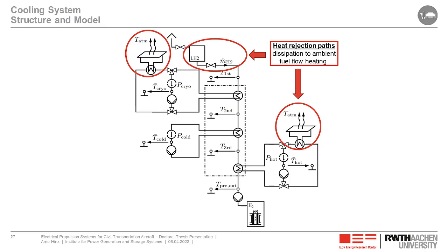The liquid hydrogen needs considerable heating before being ejected to the fuel cell, and this is done by a fuel preheater. The actual output temperature of the fuel preheater is dependent on the pressure rating and operation temperature of the fuel cell, as we need to achieve that temperature after the compressor.